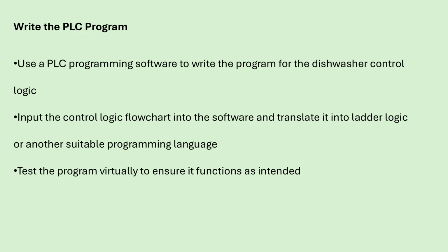Virtual testing. Before uploading the program to the hardware, test it virtually using simulation tools available in most PLC programming environments. This helps ensure the program functions as expected without risking damage to actual components.